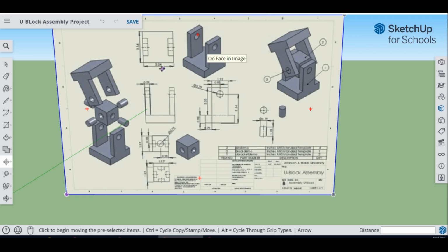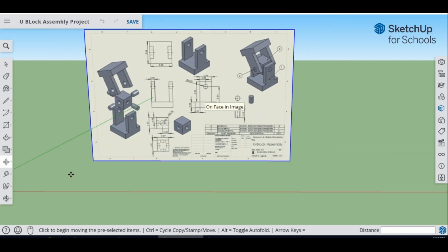You can see that the base design is 3.54 inches by 3.54 inches. The thickness is 0.98 inches. Once we draw that, then we're going to be drawing these two images right here. How we're going to do that is we're going to measure with our measurement tool 0.79 inches over, put a mark, and then from that mark, we're going to draw a square that is 1.97 inches by 0.59 inches. Once we do that, we're going to pull it up 3.35 inches.